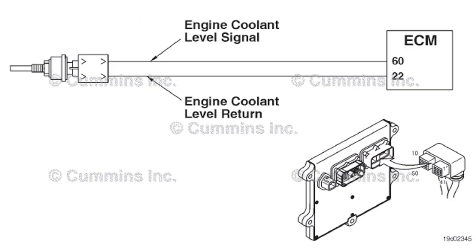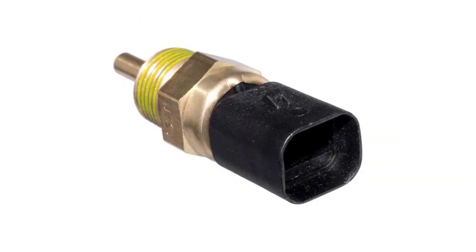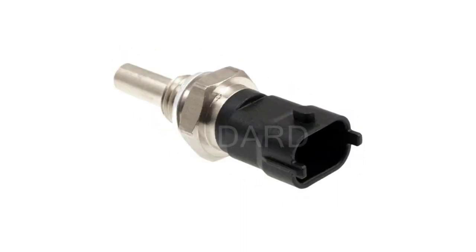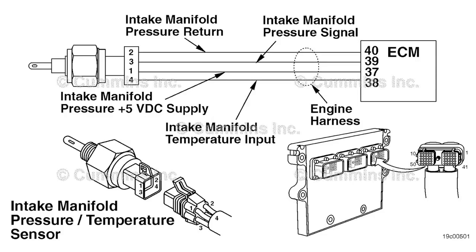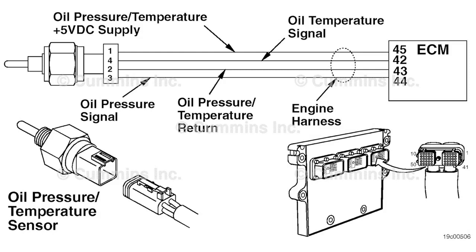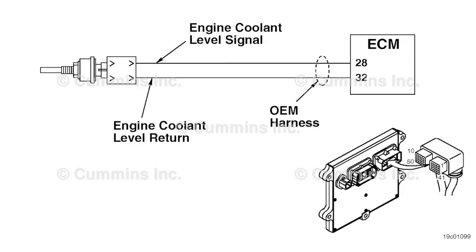The problem may be with the ECM. Use a diagnostic scan tool to check for any ECM fault codes related to the engine coolant temperature sensor circuit. If there are no fault codes, check the ECM power and ground connections. If the ECM is faulty, it will need to be replaced or repaired by a qualified technician.